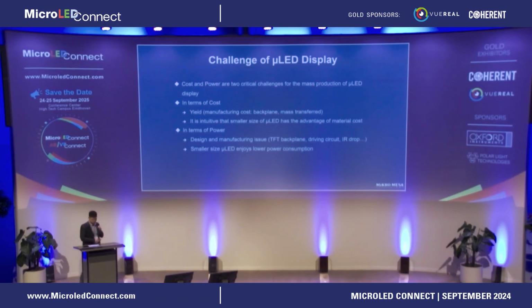And power-wise, the power loss happens in many different ways, like the TFT backplane, the driving circuit, which is very critical here, and the IR drop, etc. Again, a small size Micro LED has lower power consumption, and this is the key point of my presentation. I will show you how important it is for a small size Micro LED from the perspective of power.